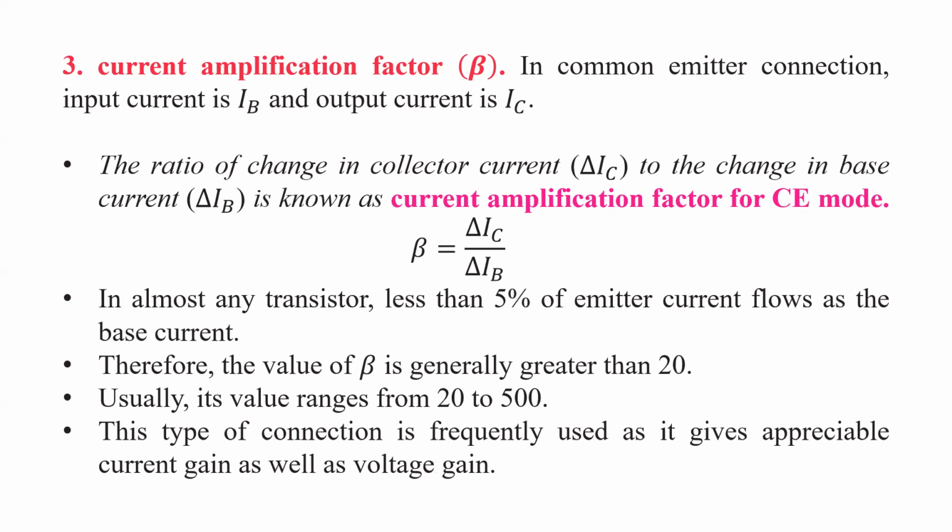So it can produce current gain and voltage gain satisfactorily, and power gain is also observed to be very high, because power gain is given by current gain times voltage gain. These are the important characteristics of this CE mode.